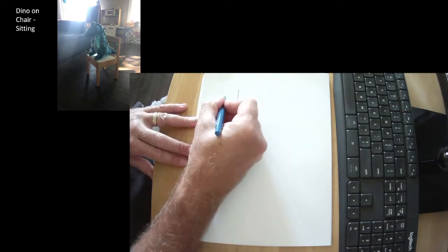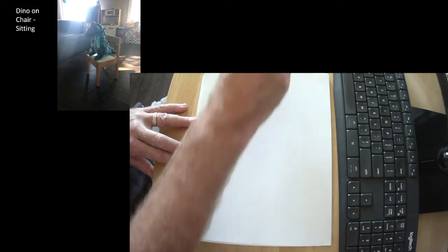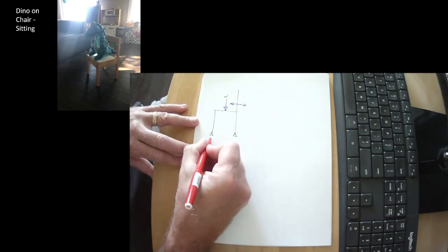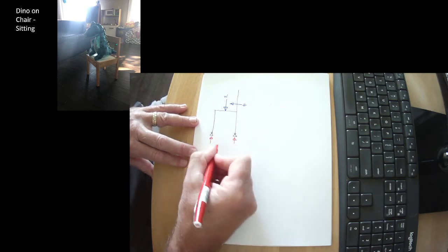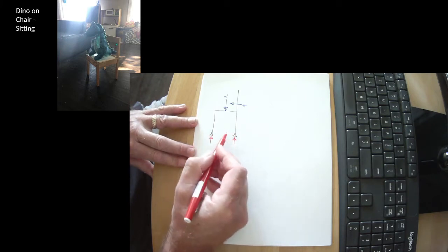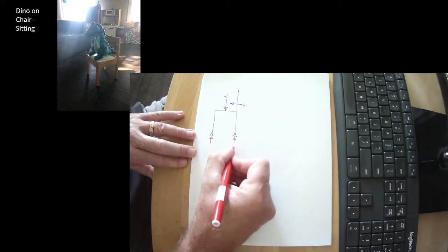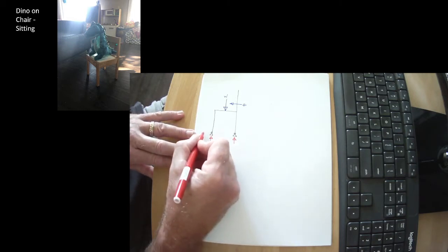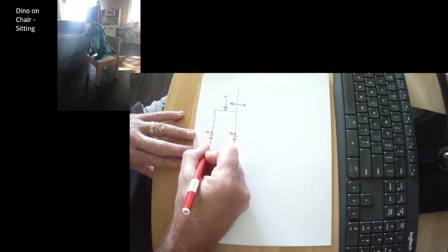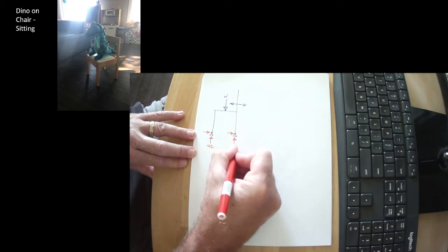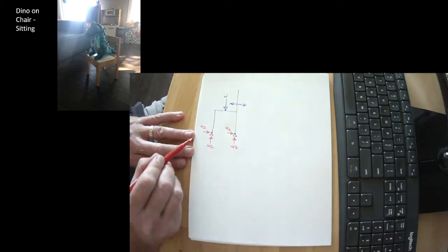We've got Dino's weight. We have a horizontal load here of wind. We have the weight component of our reaction distributed equally between the pair of legs, or the pair of pairs of legs, of course. And then we also have, so this is W over 2, W over 2, H over 2, H over 2. Now, what's missing?